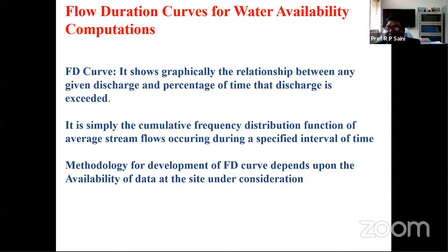It depends upon the size of the plant. If you are talking about a few kilowatts, say 5 kilowatts, 10 kilowatts, I will not say that you do this exercise. You just go for 2-3 days and observe, or you can ask the local people what the trend of variation of discharge in this stream is, and depending upon that, you can fix the plant capacity.